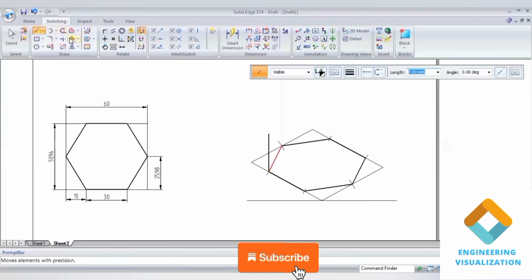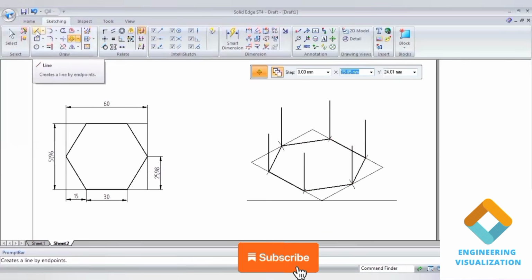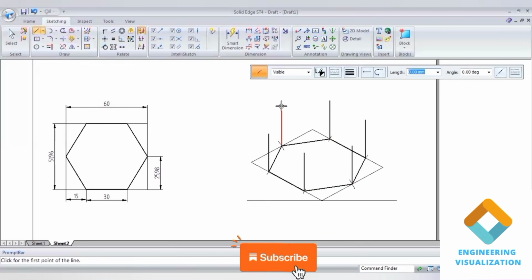Okay, we go to the move command, with copy, select the corner end and then place it with respect to all the corner points. Okay, now using continuous line I'm going to join all these corner points. Okay, so that completes the hexagon.